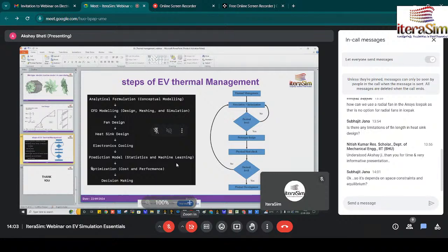It is mostly material based. If you put a highly conductive material between two interfaces, it will increase the heat transfer rate, or the conductive heat transfer. Otherwise, if there is a gap or a lower thermal conductivity material between them, it would reduce the heat transfer rate, the heat dissipation rate from the body.